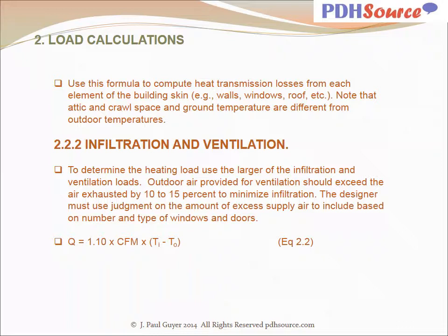Infiltration is outdoor air that gets into the building inadvertently, and it is, in the winter, cold, and that air has to be heated up, and that becomes part of the heating load. Ventilation is outside air that you intentionally bring into the building for air quality purposes.